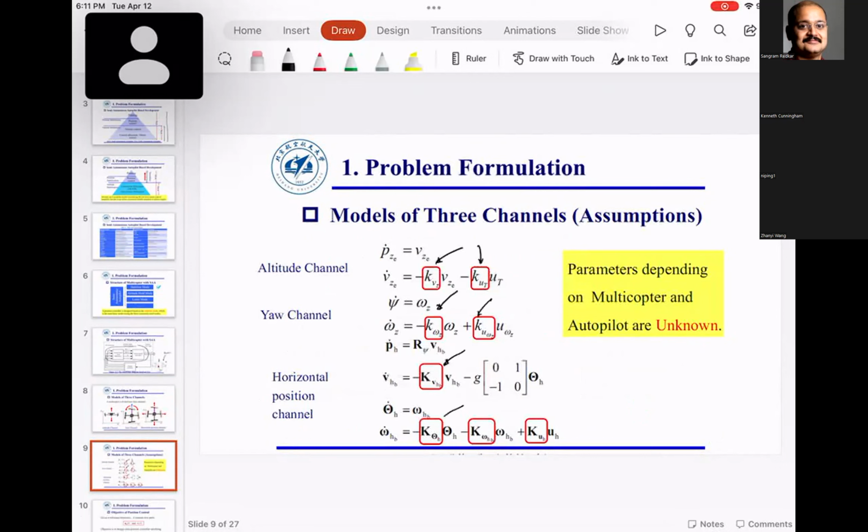And these controller gains are utilized to control the approximate dynamics of the quadcopter. Now, once again, let me repeat. The original quadcopter dynamics is highly nonlinear. But since we have this highly nonlinear system running, or sampled, at a very high update rate, we can work with a linear approximation and still be able to control the quadcopter with the PID loops.